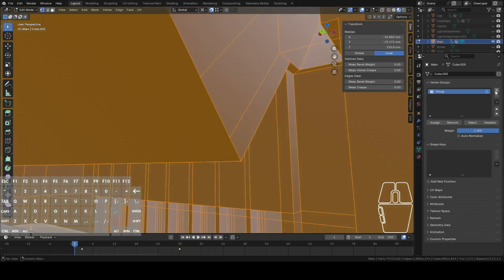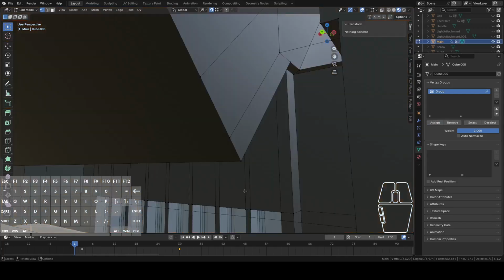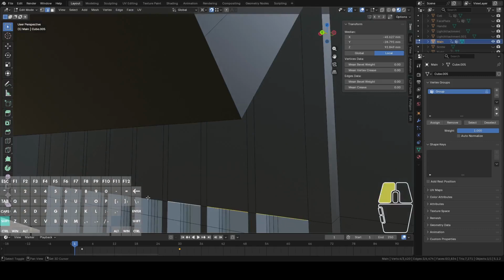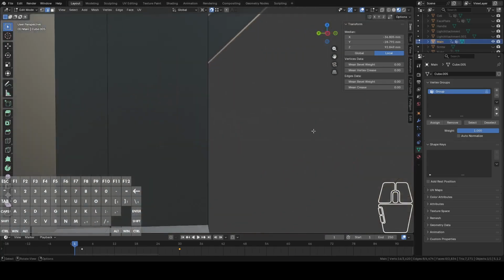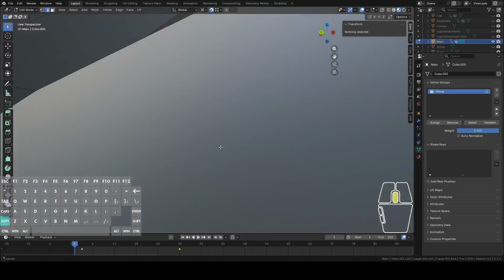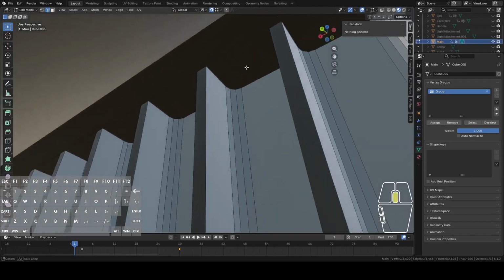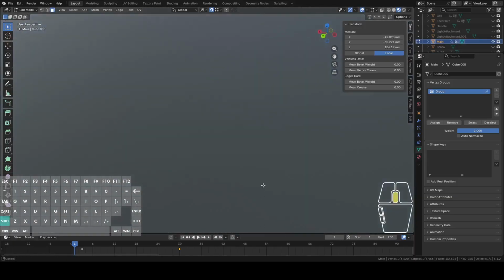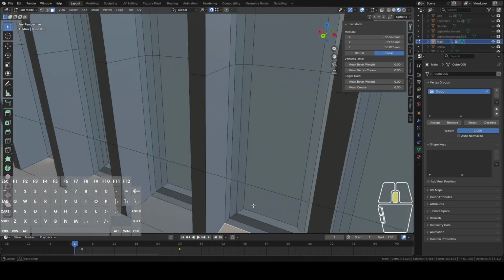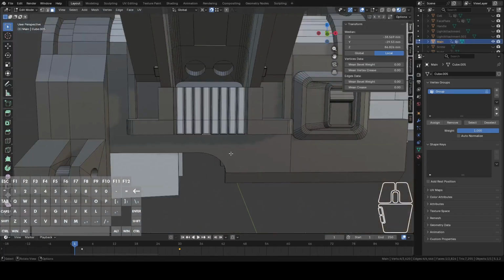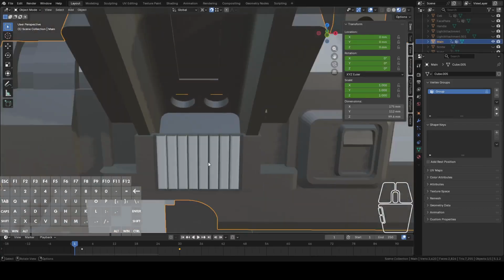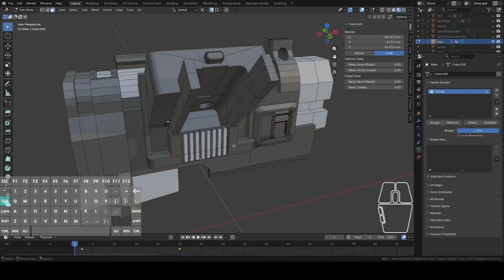So let's go ahead and make this into a vertex group. Assign, because I think I just found a location where the printer was having a little difficulty. This part was so small it's hard to tell, but I think this is some internal geometry that we can get rid of. These faces here, to clear that up. See, that's on the outside. And these should also be on the outside, so that should be good. Didn't mess things up too bad, but just gives us a nicer, cleaner model to work with.